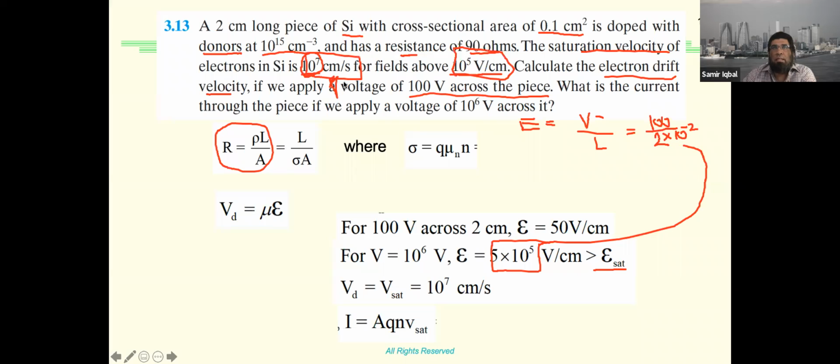All right. So a few things. Now let's start solving what is given and what's missing. We know resistivity is 1 over conductivity, and we know conductivity you can find like this, and we have everything. We know the electric charge, the electron charge of 1 electron. We know the mobility. Oh, we don't know the mobility. Mobility is what we have to find from here. So here we don't know this, but we know this guy and we know this guy. So you plug that in here and we get the mobility.